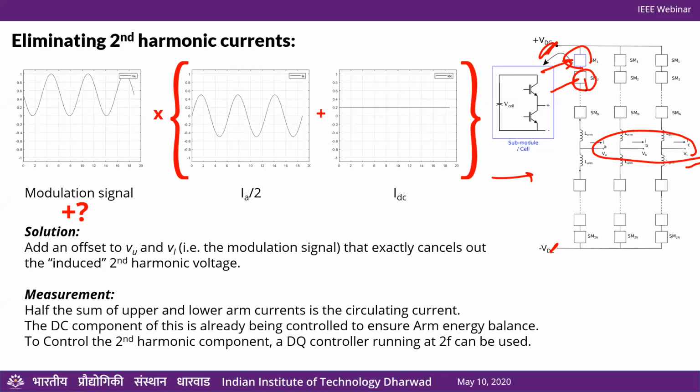That is a big challenge, because the same current is flowing through all the modules, and you want them to be generating roughly the same voltage, right? So if their power varies, then we have an issue. If you have partial shading in PVs and all that, then it's a little challenging. There are people who have addressed it, and I would recommend you look at some of the research papers to get some idea about that type of converter, but it's not exactly MMC in the strictest sense.